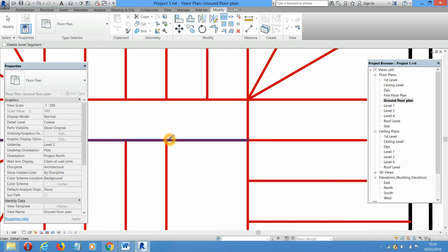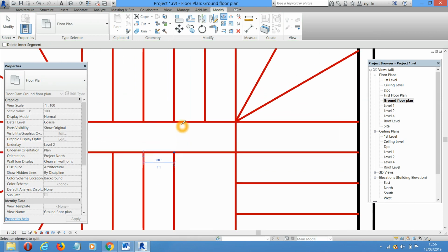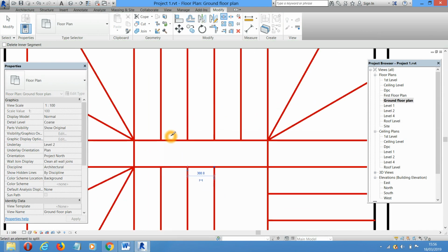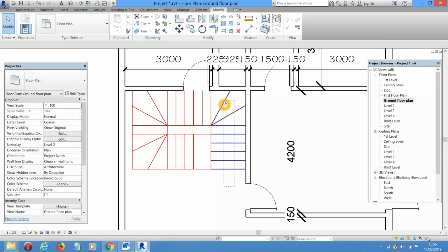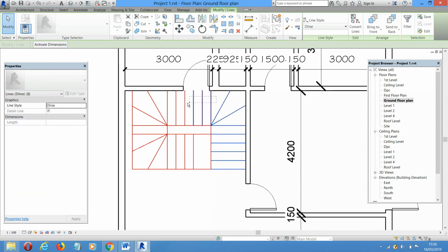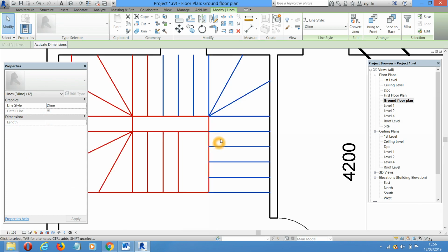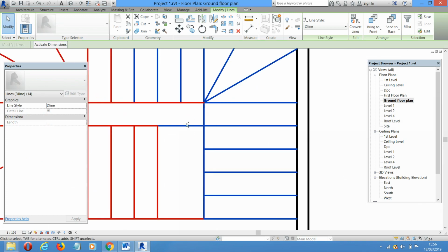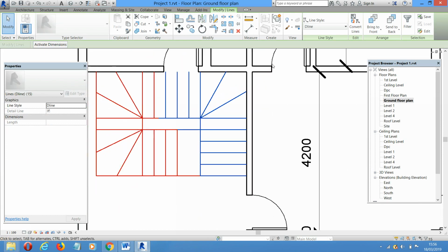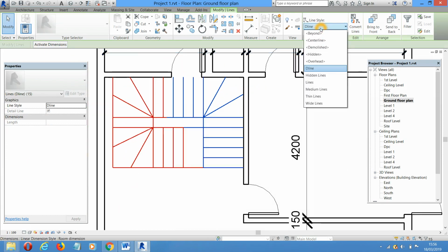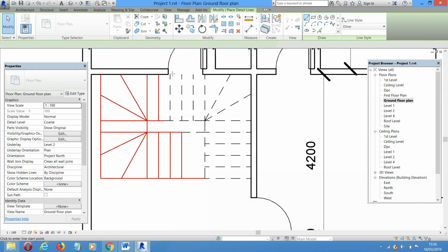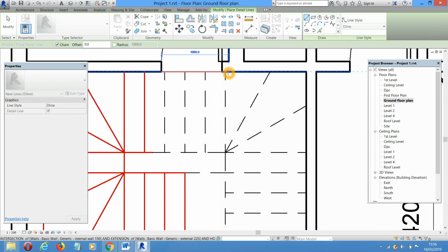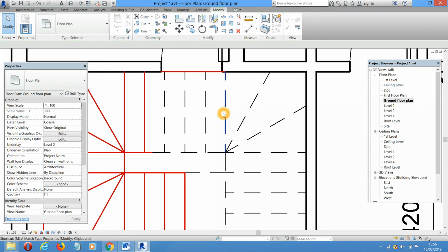I'm going to use slice to cut this one, because we are going to have a dash line to show the risers that are overhead. So I hold Control to highlight all these ones. All these ones are going to be dash line, and in choosing my dash line, I select overhead. Then I'm going to close this one up, and I'm going to match property.